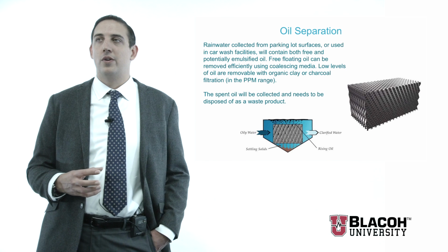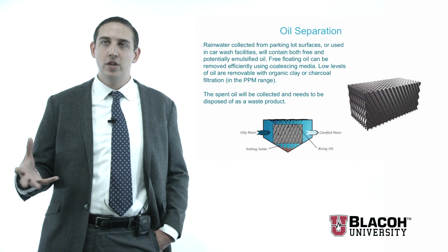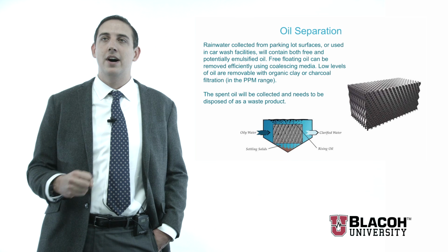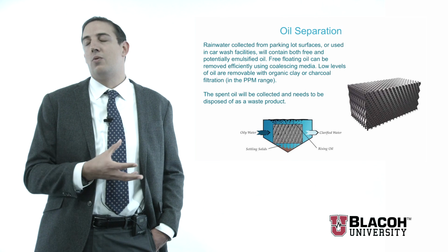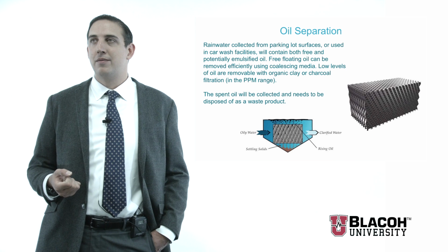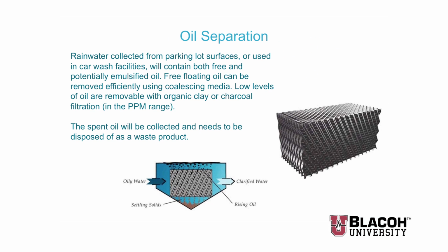If you're using stormwater in place of rainwater, you really ignore all that stuff about roof catchment surface and filters, and you go into more oil-water separation. The first thing you have to do is remove all the oil, antifreeze, and other chemicals which are going to run off from your stormwater source. And these act as your pre-filter in those cases.